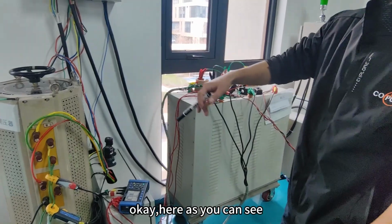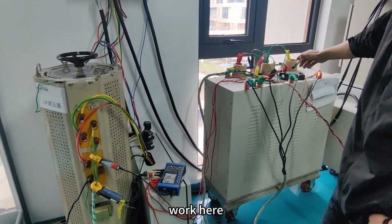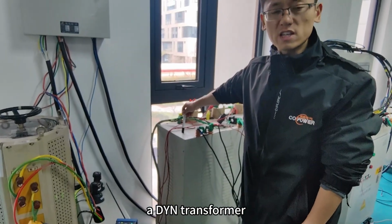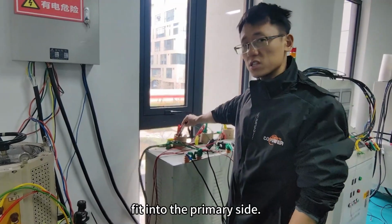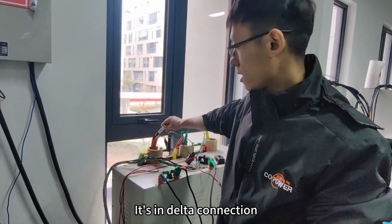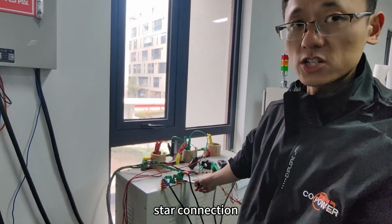Okay, here as you can see, we have made an experimental setup. This is the transformer, which is also a DYN transformer. The voltage supply goes into the primary side, which is in delta connection, and the low voltage side is in star connection.